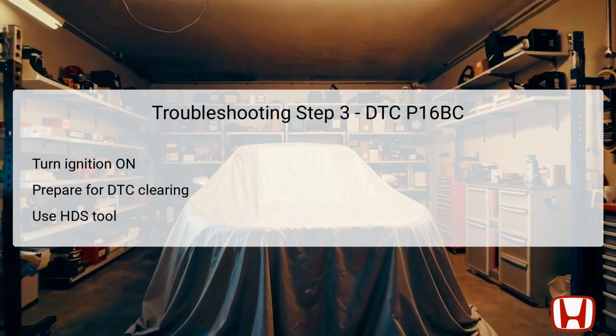Clearing the diagnostic trouble codes should be performed next, as this prepares the system to re-evaluate the conditions that triggered the initial DTC. Using the HDS tool enables technicians to interact with vehicle data effectively and monitor changes after repairs are made. This standard procedure helps to understand the current state of the vehicle's systems, ensuring that any further actions taken are based on updated information.